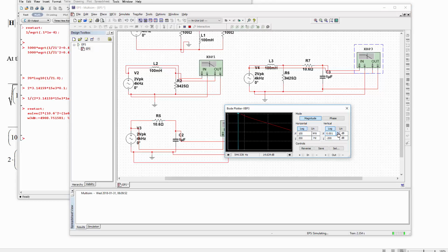Let's increase the top here up to 2 decibels and even higher. So what's going on in this circuit is that we have some resonance effects at the lower end. So it's not only low pass filtering, but it's giving us gain of a pretty significant amount. This is going to a 23 decibel gain at this one resonant point there.